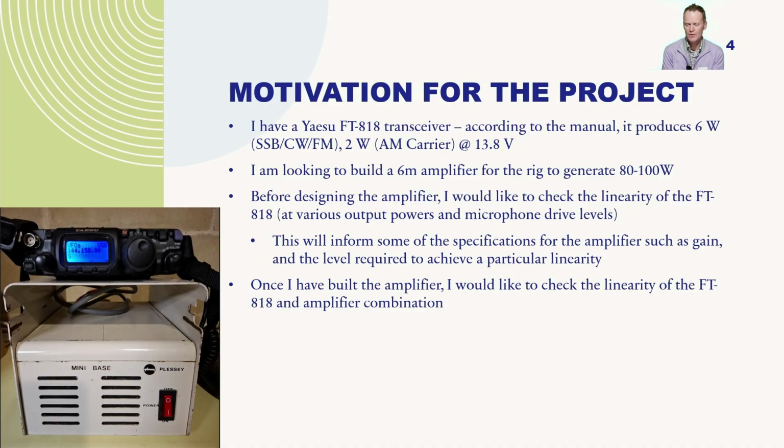But before I designed that amplifier, I really wanted to check the linearity of the FT-818 at various output powers and at various microphone drive levels. And the reason for this is that it's going to inform some of the specifications for the amplifier, such as the amplifier's gain and the level required to achieve particular linearity. Thank you very much, Peter. And then once I've built the amplifier, I'm hoping to check the linearity of the combination of the amplifier and my radio together. So that was what the driver was for this project.